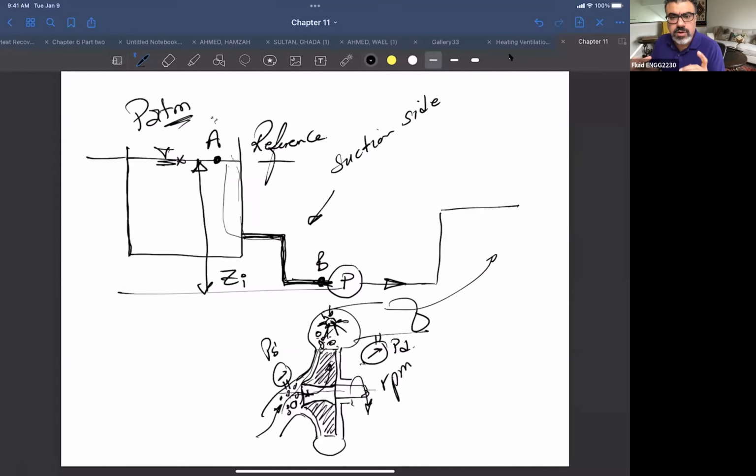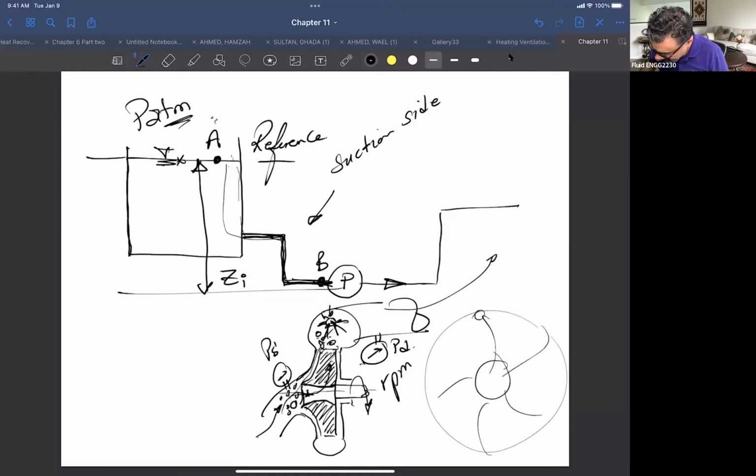That's why when you look at a pump that is suffering a lot of cavitation and you open the pump, you will see at the exit part of the impeller, if you look at this impeller here, a lot of damage in this location because of the cavitation, right?